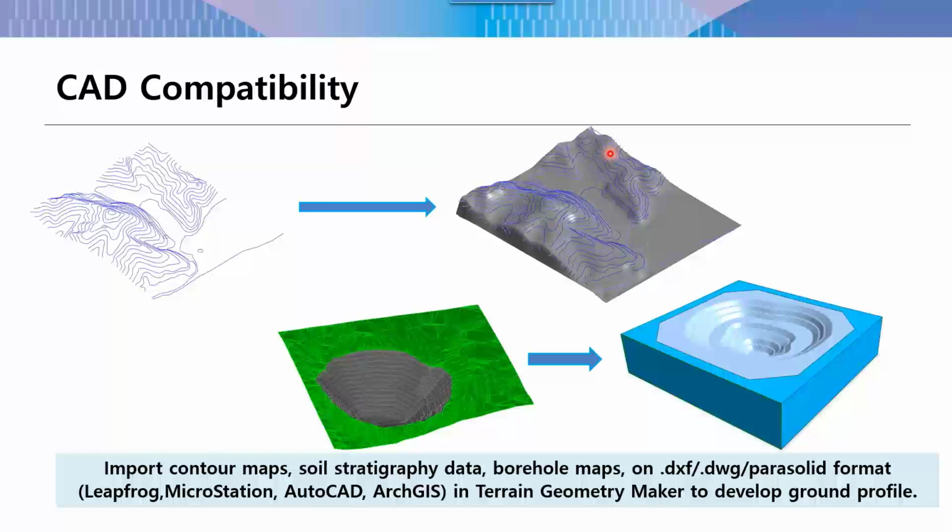Otherwise, if you have a large area, which is also called a stringed or a triangulated area, which is basically an output of either GIS software or software like Leapfrog, Minex, Vulcan or Surpac, in those cases you can export these large triangulated digitized string surfaces to GTS and get done with your faces. And actually, Civil 3D is also right now able to make these kinds of stringed faces for large area distribution.